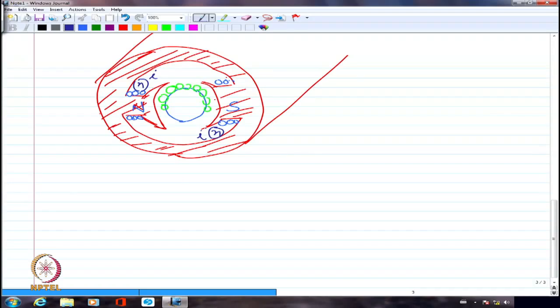Some same current I is probably going to flow through this as well. So, I will have in all probability 2Ni as the MMF in this case. I am showing two poles, each of them consisting of N number of turns, and both of them carrying a common current I, if I connect them in series. So, this is going to be the MMF.